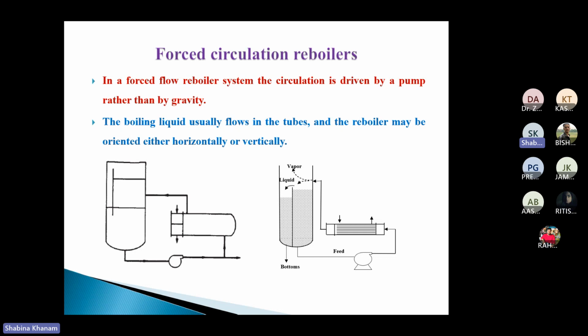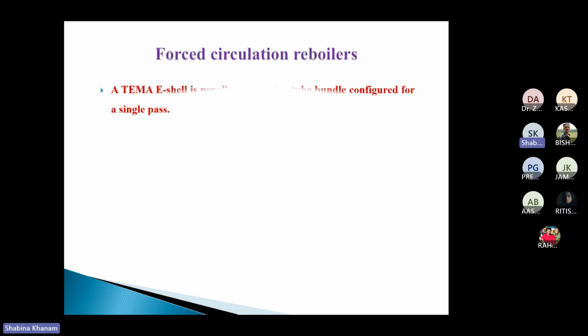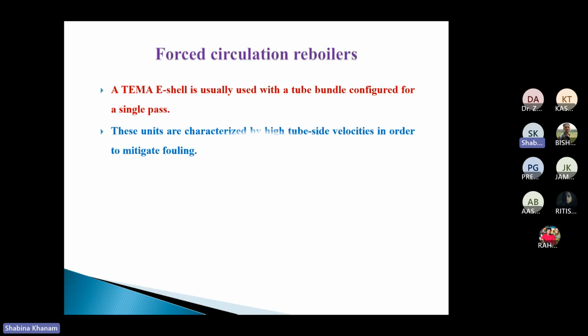Pump will maintain the circulation. Okay, but in what condition do you need to consider this forced circulation reboiler? When we are dealing with a high fouling tendency liquid. When the fouling tendency of the liquid is high, it is difficult to circulate on its own.